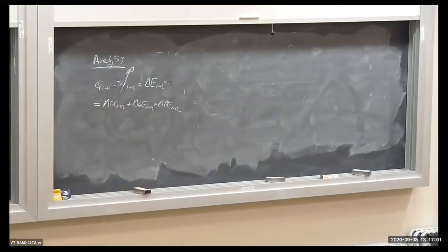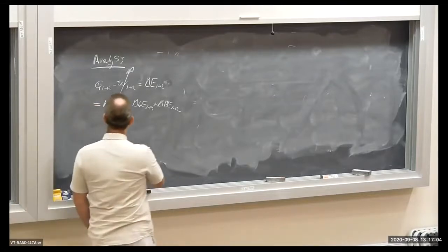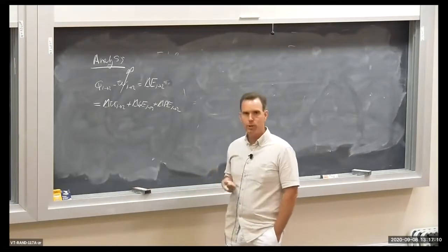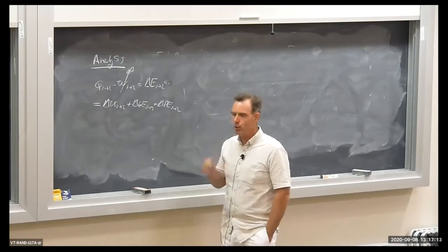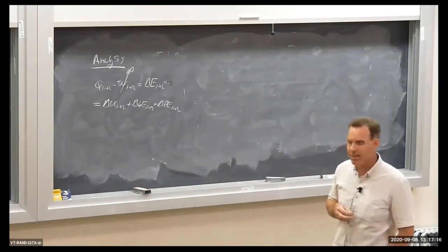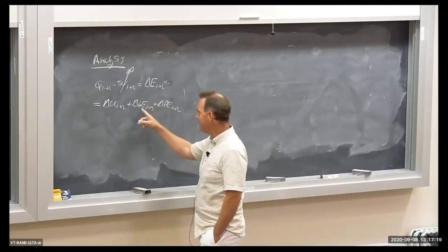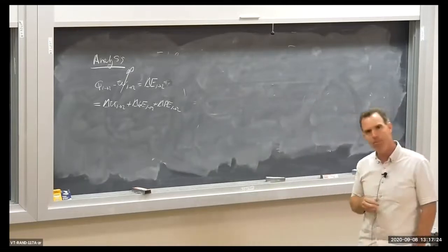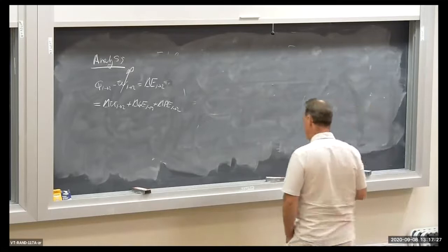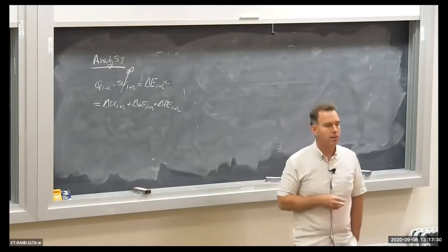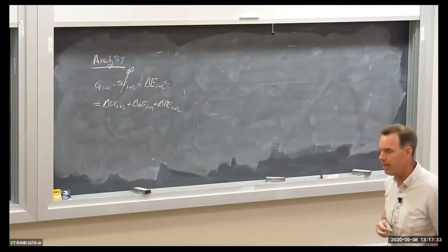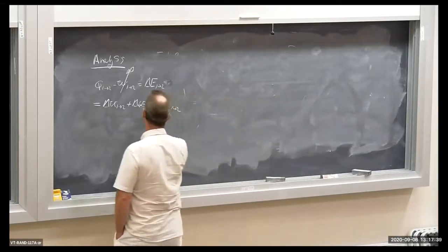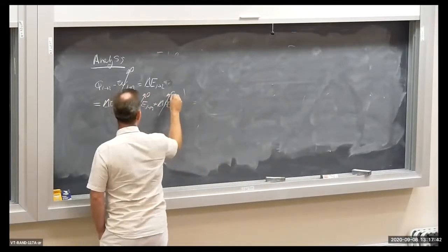Okay, let's attack some of the other terms here. The change in internal energy has to do with the change in either phase or temperature of the system. The temperature of the system is definitely changing, so I don't think I can get rid of the delta U term. But I can, I think, neglect the change in kinetic and potential energy of my air system. I don't get any sense in the problem that the air is moving, that it's accelerating, that it's slowing down, and I certainly don't get a sense that the position of the tank or the rigid container is moving. So there's no change in gravitational potential energy of the system. So I'm just going to assume these away.